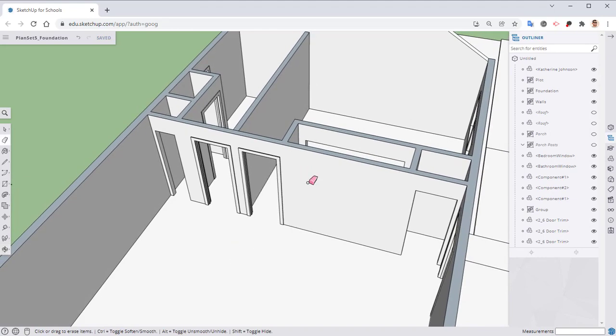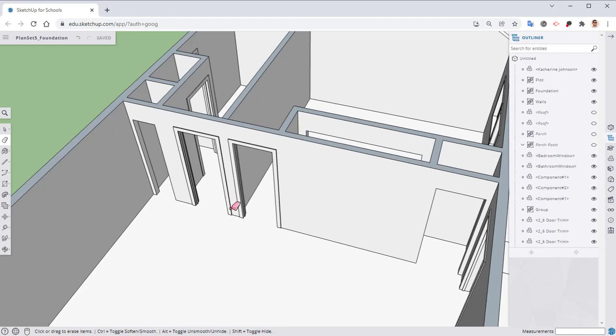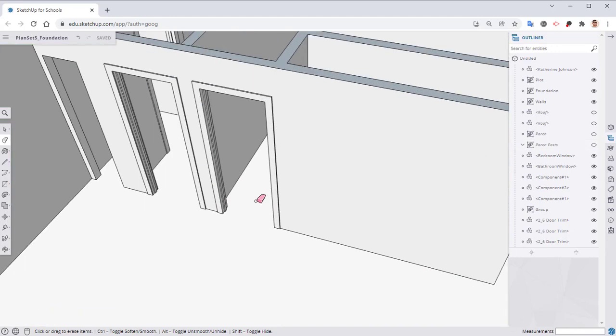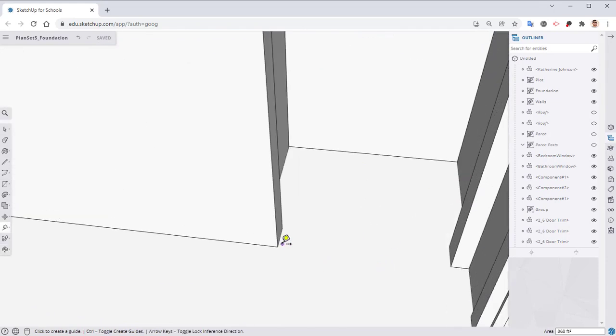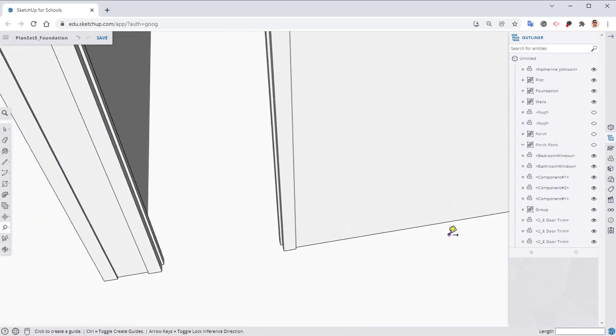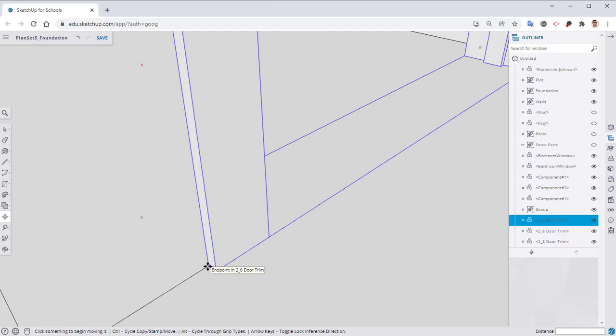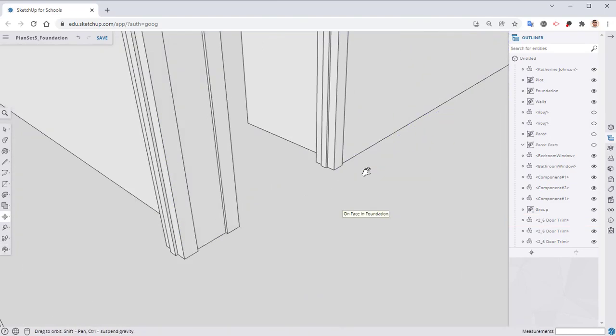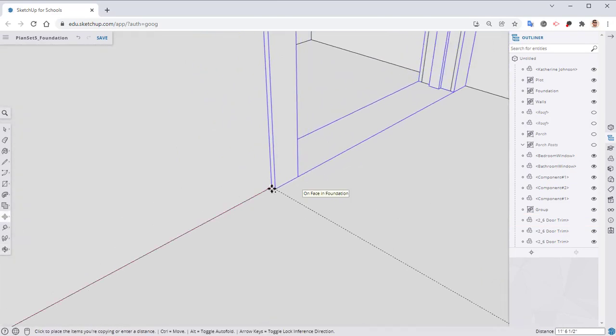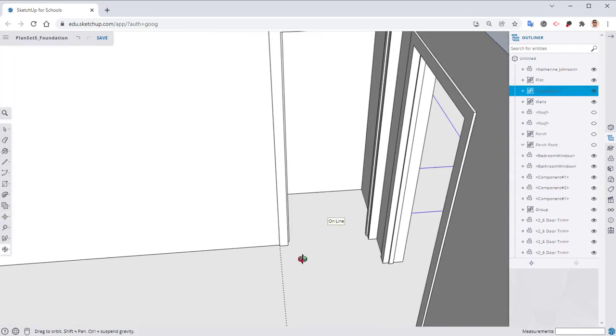And now we just have our two other doors that we need to do. We still have this over here, so let's go ahead and do the same thing. So let's tape measure. This one is 2'6" again, so we're going to mark off our 2 inches. Select your move tool, hover over this corner, hit Control, drag this over and place that there.